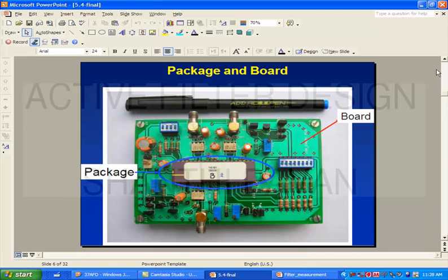There is a whole bunch of them, you may like the Z parameters, you may like the H parameters, you may like the Y parameters. It turns out that for measurement work, people like what are called the scattering parameters or the S parameters. This is one more manipulation of voltage and current. At this point I will not get into the details of S parameters, but all I will say is that just like you can convert from Y to Z and Z to H, one set of parameters to another, you can also convert from Y to S.